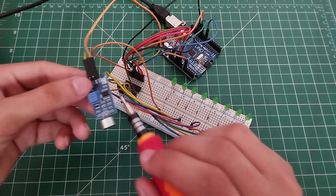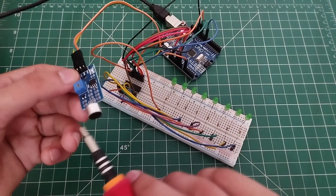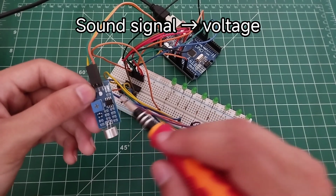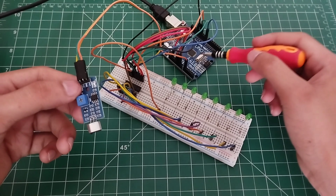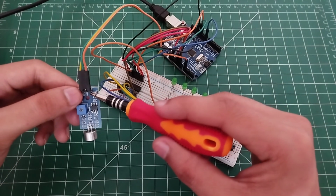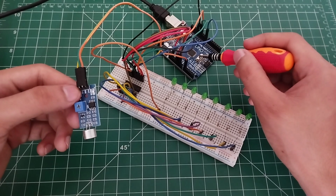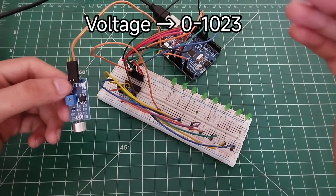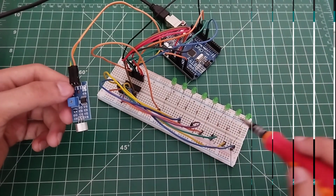Now here comes the interesting part. In this project we are using this microphone module, which is basically a sound sensor. What is the job of the sound sensor? This module collects the surrounding sound and this onboard chip converts that sound signal into a voltage level, and that voltage level is read by the Arduino. You can see this output pin is connected to pin A0 of the Arduino. The Arduino converts that voltage into a decimal number from 0 to 1023, and based on how loud the sound is, we light up all these LEDs.